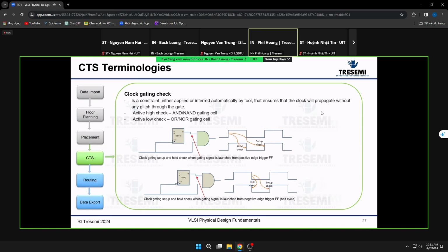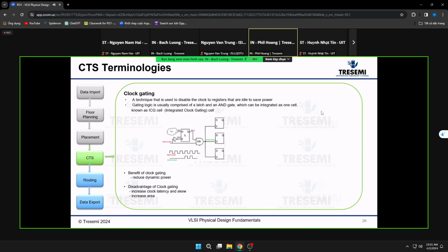Yeah, and also it's just for your awareness, but the tool can fix all the issues, right? Yeah. So you must use clock gating to control the power. There's no question about whether or not it should be used for a power sensitive design.